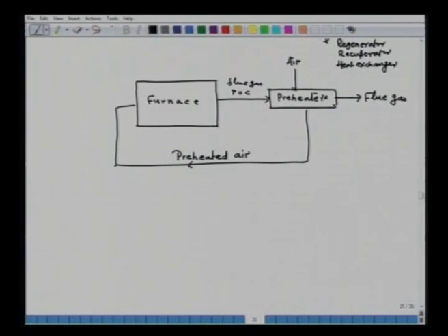Now, the total air required for combustion is equal to 0.595, as I wrote down earlier. Here the air leakage is 15% of theoretical, so you have to calculate the theoretical amount. The air leakage, as I wrote earlier, is 0.0714 kg mole.